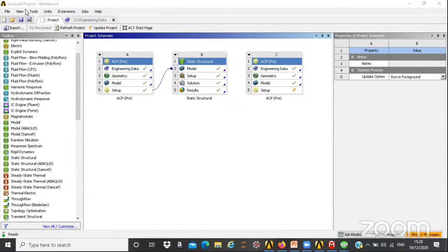Electronics people work the other way around. We have to fix the output to what we want, and the input variables are automatically manipulated in such a way that the output is achieved no matter what. That is what happens in automation. For that we firstly need a transfer function, because these regression equations are not understood by controllers. We need transfer functions many times, and other functions also in control theory, to firstly model the system in terms of those multi-input single-output or multi-input multi-output systems. And then we have to put them into controllers, and then controller parameters have to be tuned so that this kind of controlling action is performed.